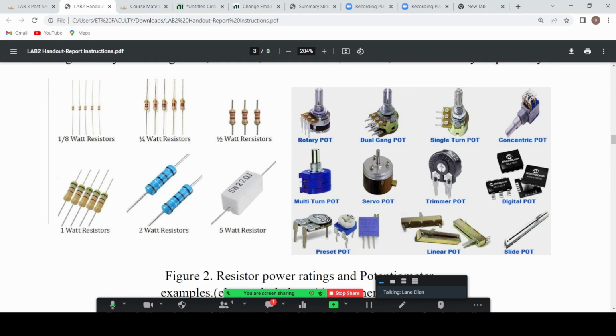The basic concept is that when you turn the selector, essentially what you are doing is changing the location of the selector pin, and that in turn changes the resistance that is coming out on these 2 pins, what it is between one selector pin and another pin of your potentiometer. You also have digital potentiometers where it's like an IC, and you can actually program it, and it's going to change some switches inside of the IC, and on two of your pins you can have the change in resistance as well.